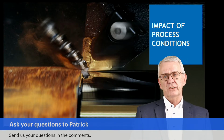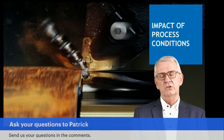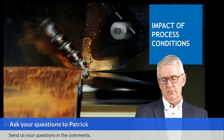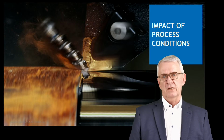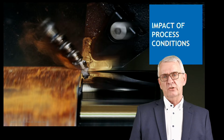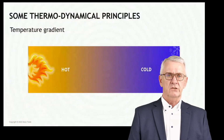And heat in the cutting edge, heat that focuses there, leads to certain temperatures in the cutting edge, which leads to a certain type of wear development. And wear development leads to a certain tool life. And tool life is the bridge to the economical side, what Professor Stahl said in the beginning with his quote. Heat and temperature, next to technical matters, also influence the economical consequences of machining.